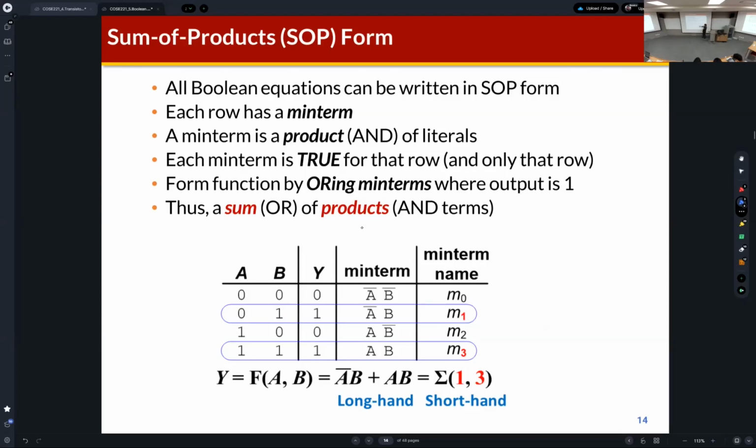So using the truth table, we can define the min term of every row, like here, and then we can select the rows that can make Y 1. Okay, so there are two lines here, this line and this line. So we can know the min term of this line and this line. Then we already know that Y becomes 1 if this condition is met, or this condition is met. So we can represent the result Y like this.